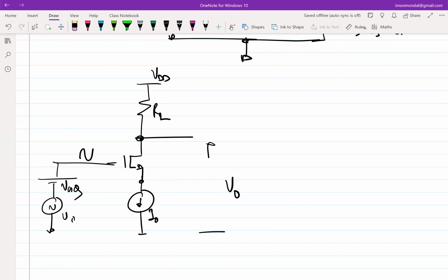Right. So if I have to short it incrementally, we know how. If we have to shorten something, you just put a capacitor between that node and ground, so all the incremental current will now flow through it. If this capacitor is large enough, let's say this C is infinity, not this small parasitic capacitance. What is large enough? We know how to figure it out. We have done it multiple times.